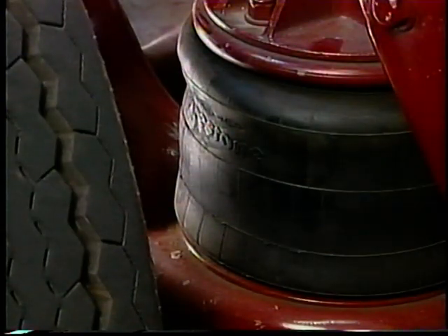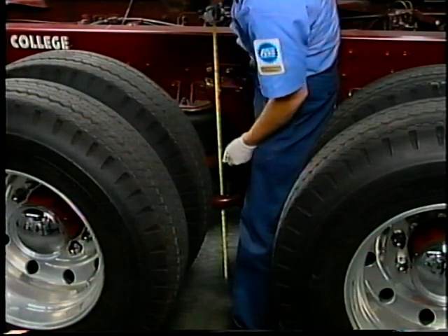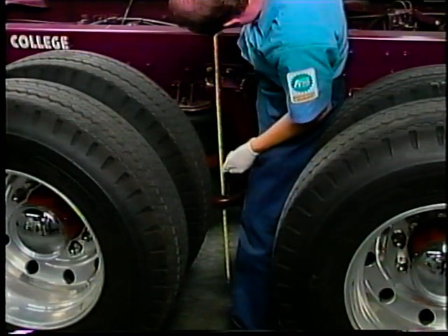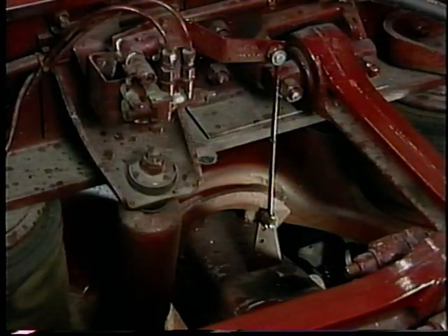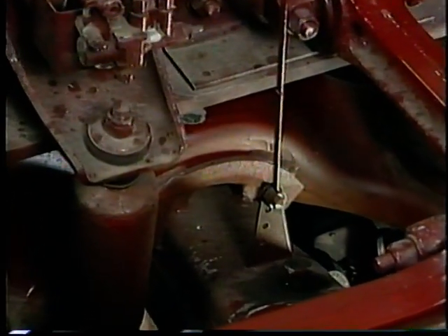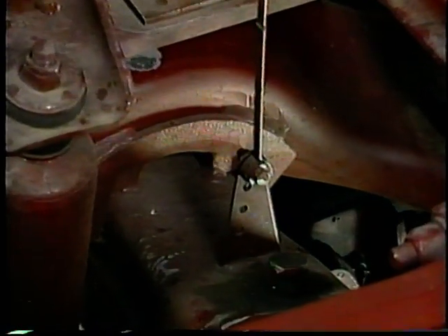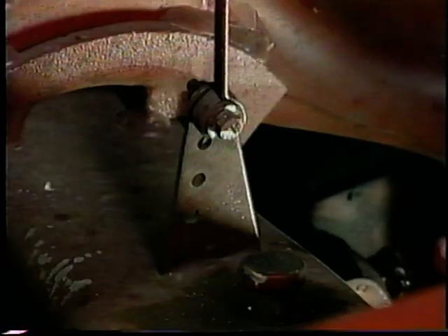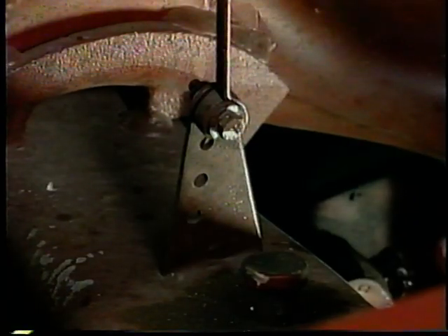Failed air springs will result in a low ride height. If the vehicle height is too high, suspect a misadjusted height control valve. A vehicle that sits too high or too low may have a misadjusted ride height control valve. The valve uses a control rod located between the control valve and the rear axle to gauge ride height.